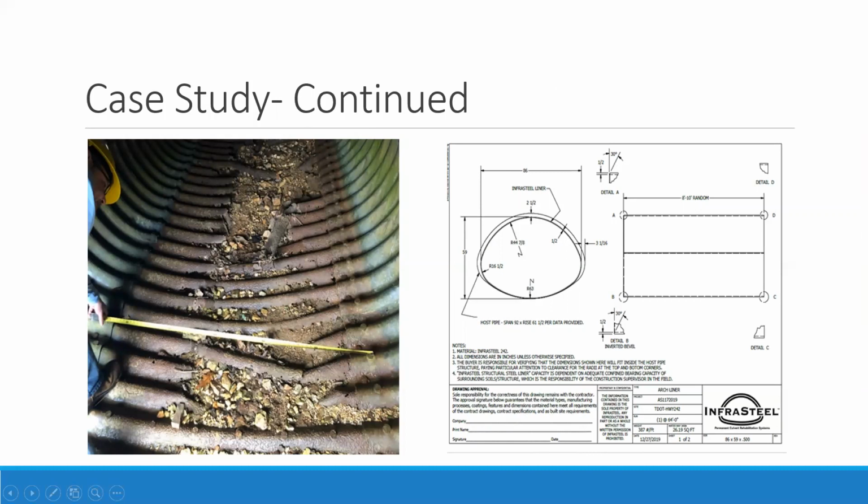The CMP culvert located under State Route 242 measured 92 inches in span with a 61.5-inch rise, a total of 64 feet in length, and was located approximately 7 feet below the roadway. Initial inspection of the structure revealed that severe deterioration in the invert had occurred due to abrasive and corrosive factors in the environment, coupled with the length of time that the culvert had been in service, which was estimated to be 50 plus years.